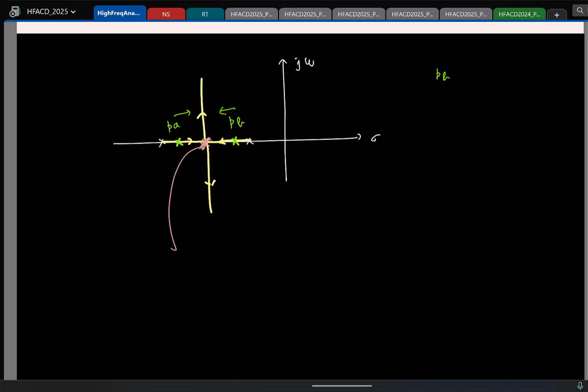And what is this kind of settling called? A second order system. Closed loop poles are exactly equal. What is that condition called? Critically damped. At least with respect to the fastest settling, this is the best condition to have, right? Is that clear? And I will give it as an exercise. You can work out and show that the phase margin for this case is 76 degrees. So this might be one phase margin to aim for. Okay.